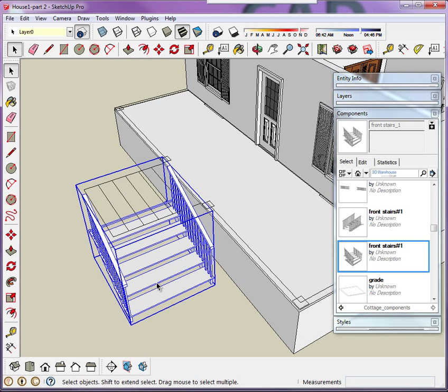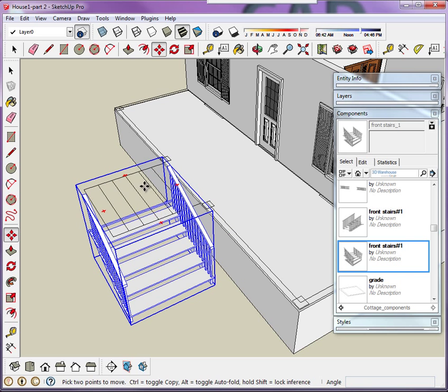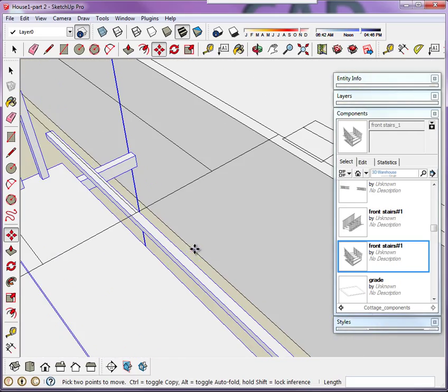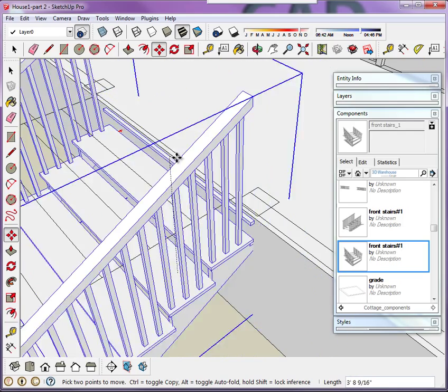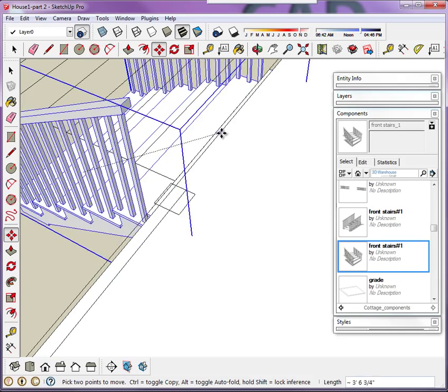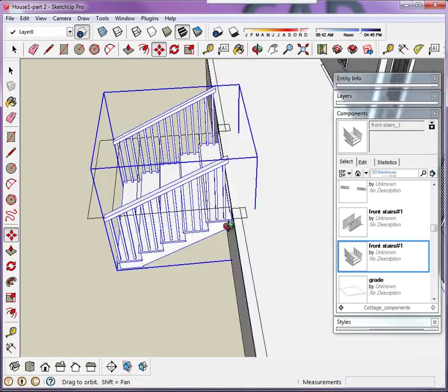And if you recall, you'll notice how when I select and I use move, if I go over the component, whichever face I'm on, you'll notice that I'm able to rotate it. So if I wanted to rotate it in position, I can use the horizontal plane here, give it a 90-degree rotation, and then notice that here's the top bull nose of the top step on the decking, and what I could do here is locate the midpoint. Okay, here's the midpoint in the component, snap to that, and then I could find the midpoint here and be able to snap to that. So position yourself in a way that you can actually see it, and notice, right, as you get closer and closer to the middle, it should snap to the midpoint in that component. Click. All right?